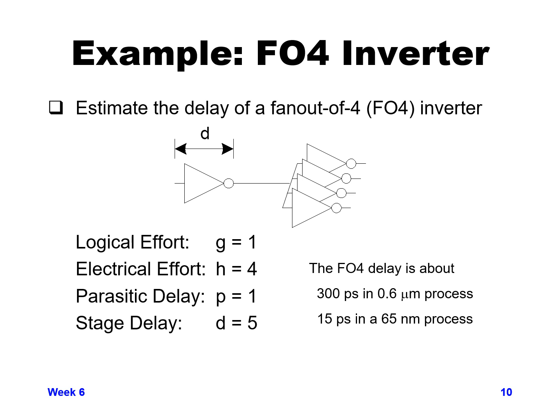So that tells you how you can do your calculations in a process independent manner and then eventually convert to the process that you're on. This is an example of how that comes in useful, where you don't need to know what process you're on in order to calculate delay of one type of gate or one type of stage relative to another. We don't necessarily need to know the absolute delay while we're trying to optimize our logic function.